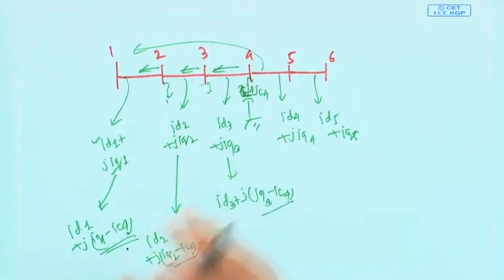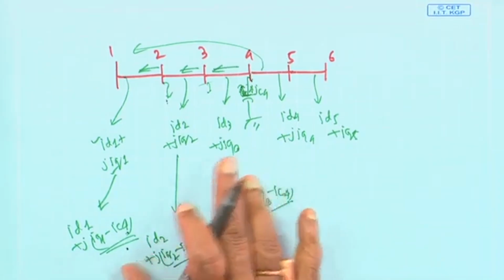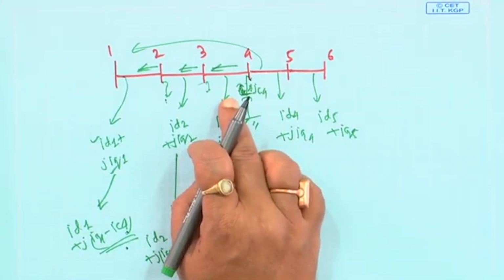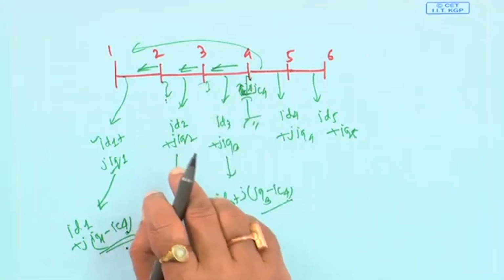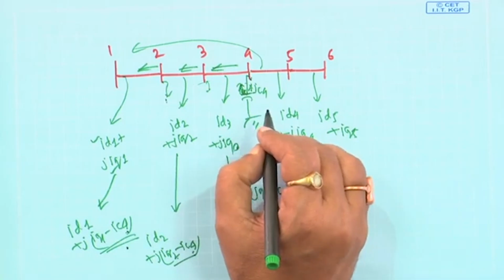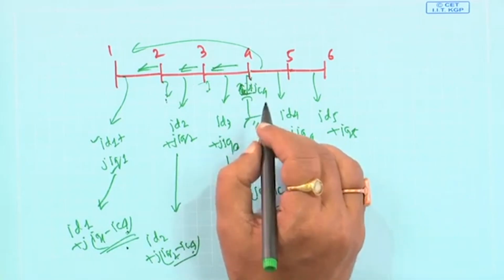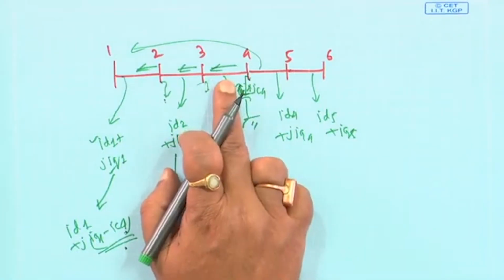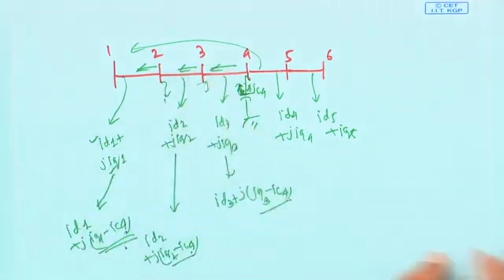This is just the basic thing. In the classroom exercise we cannot show all this without the help of a computer, because we need a large network. But keep in mind that the effect of a shunt capacitor is local. Local means that in the nearby region the power loss reduction will be maximum, but as you move far away, the percentage loss reduction will be low. The main purpose of a shunt capacitor is to reduce the power loss, and though not much, it improves the voltage magnitude, because every branch has less current, therefore less voltage drop. Therefore, to some extent the voltage also improves.